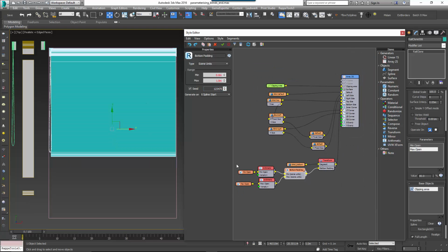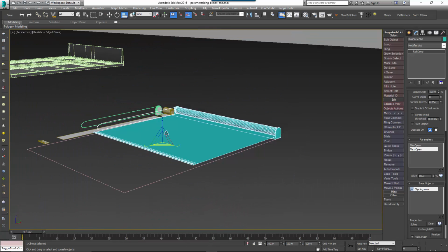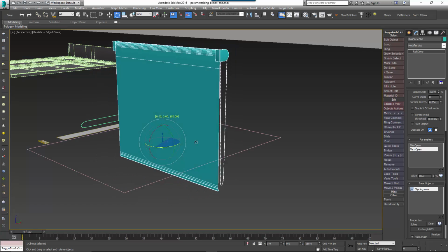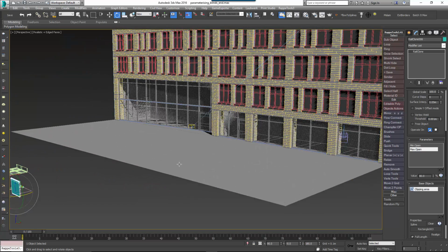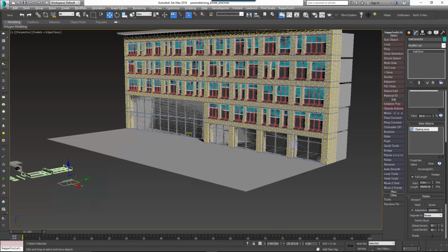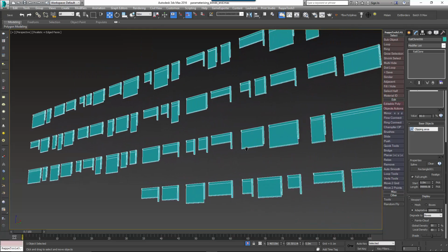So the beauty of this style is that we can easily apply randomized blinds to an entire facade. So in this case, we just want to make sure we rotate the whole style so that the blind would face inside the windows when it's projected onto the facade, and then change the clipping path to the window spline, and that's it. Instant blinds with randomized open sizes with an easy to adjust minimum and maximum range derived automatically from the window's height.